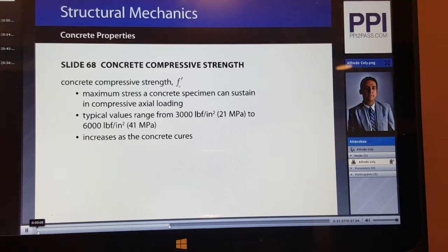What can sometimes be done during construction projects to accelerate your schedule, because you need to wait about 14 days for concrete to reach its design strength, is that the compressive strength can be tested earlier than those 14 days, perhaps at 7 days, or 5 or 6 days.